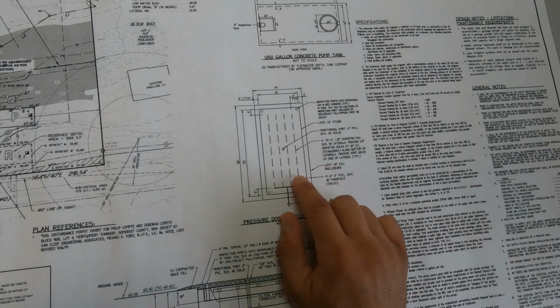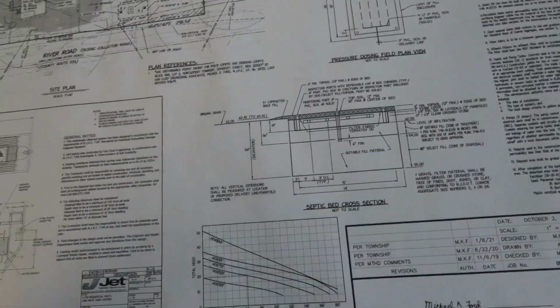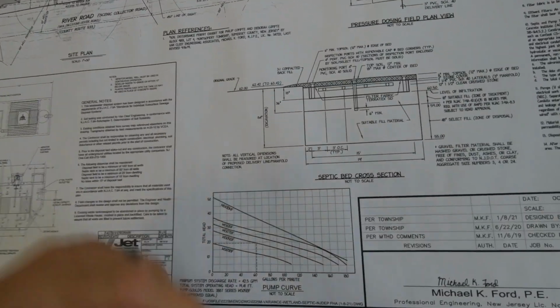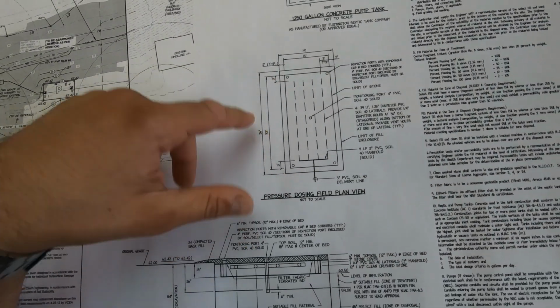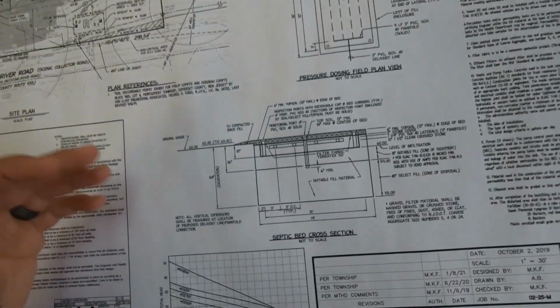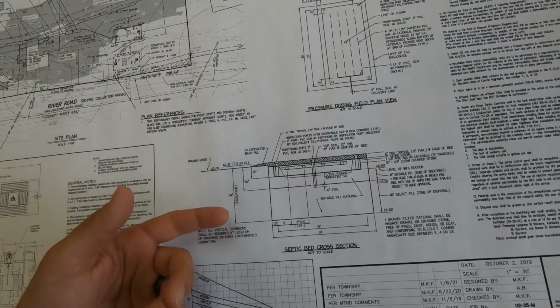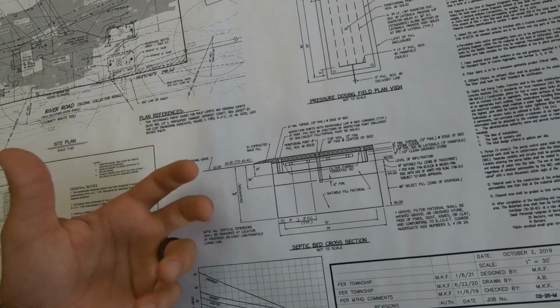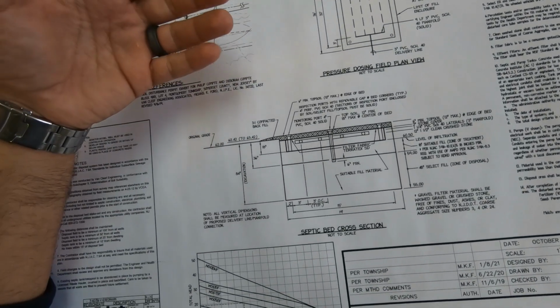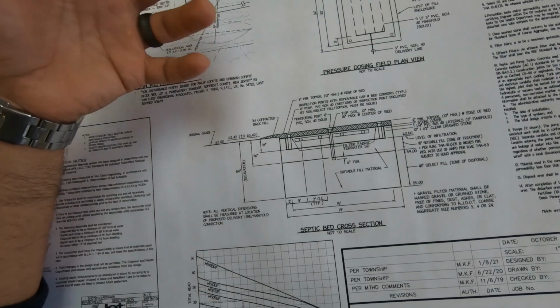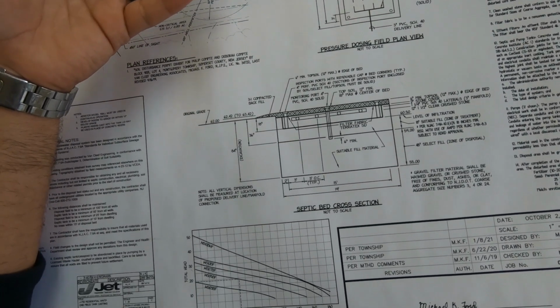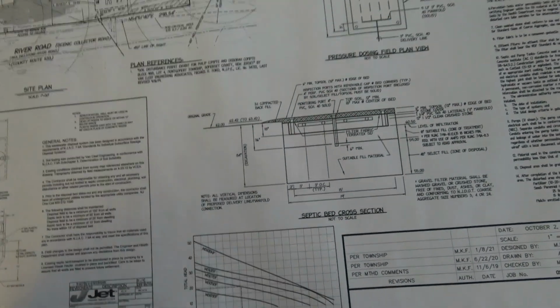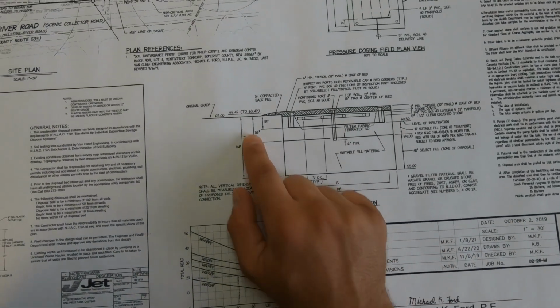You want to verify the size of the hole and the depth of the hole. A lot of the time, I'll use a tape measure to measure down into the hole, and I'll use either a wheel or a longer tape measure to measure the dimensions of the field. Sometimes the contractor has their speed leveler set up, it's basically like a leveling rod that has a device attached to it that beeps when it's at the proper level. You can have them verify the depth of the field using that if you'd like. But again, this cross-section detail shows the excavation depth.